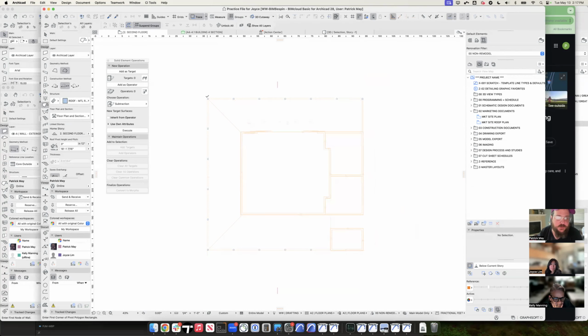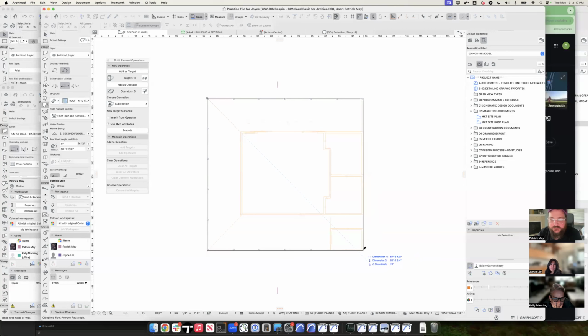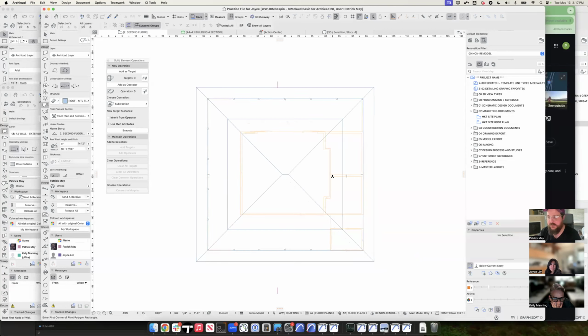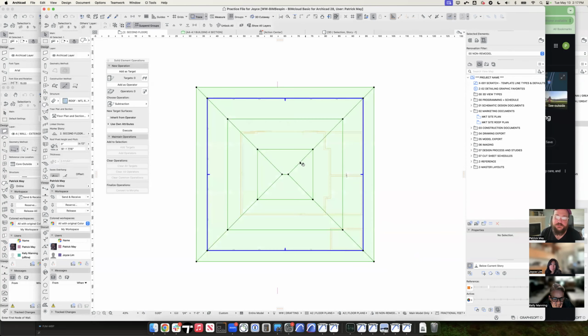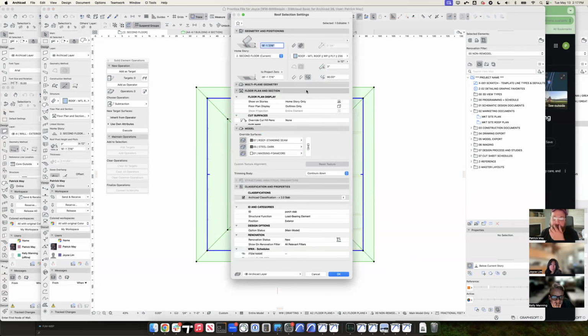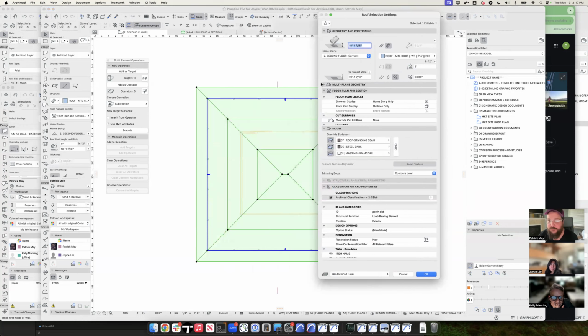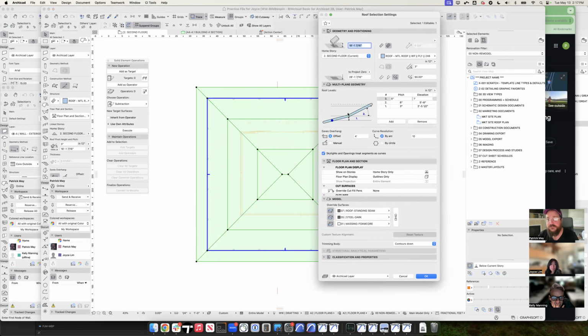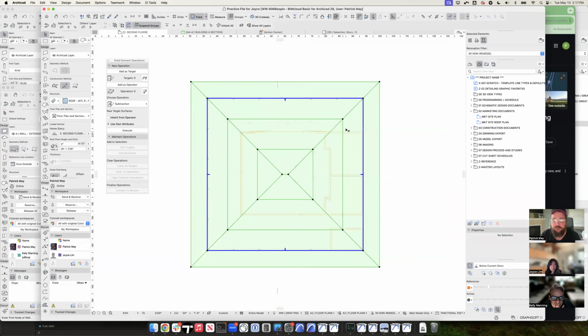And then from here, I don't have to define the reference line. I can just click across and make it a rectangular roof. This is really the advantage to that multi-plane roof, that really quickly you get basic hips and valleys for any shape that you need. It does have that reference line, but also it has the ability to just universally say we want to have a 6-foot roof overhang, right? And I don't have to go through and adjust all of the roof overhangs individually.